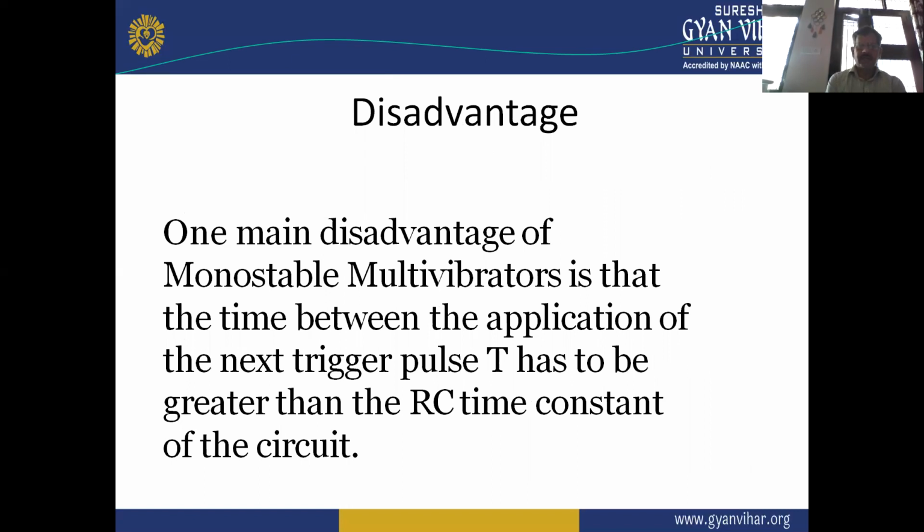And there are also some disadvantages of the monostable multivibrator. One main disadvantage is that the time between the application of the next trigger pulse T has to be greater than the RC time constant of the circuit. So this is the one main disadvantage of the monostable multivibrator.